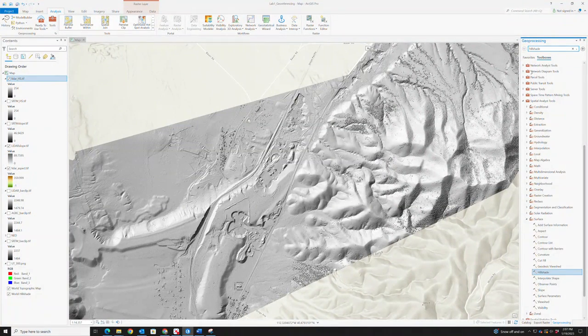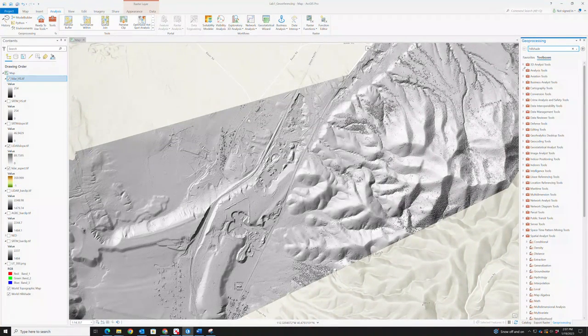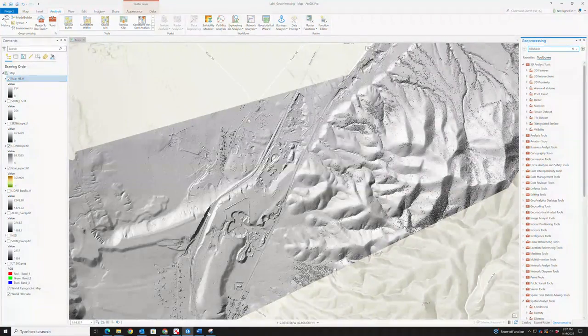To do that in ArcGIS Pro without purchasing outside tools, you need to use 3D Analyst tools. And basically what you need to do is make the lines that you want to profile across your image. And then you need to intersect those lines to make them 3D features. And then from that, you can draw a profile. It's cumbersome. I'm going to show you two other ways that you can do it. That way is articulated in a tutorial posted to Canvas or linked to your lab.